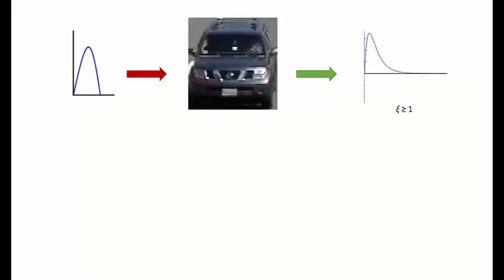But to design a suspension system that does not give any oscillations at all, you have to fit a damper that drains all the jerks. You also knew that in such a case where zeta is greater than 1, that is, the damper drains all the jerks, the damper will soon lose its capabilities. So you are able to convince your boss that the dampers in the suspension system of such a vehicle cannot survive long in the condition of the roads that we are having, and sooner they will require a change.